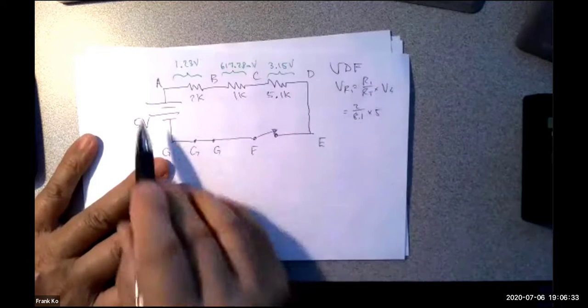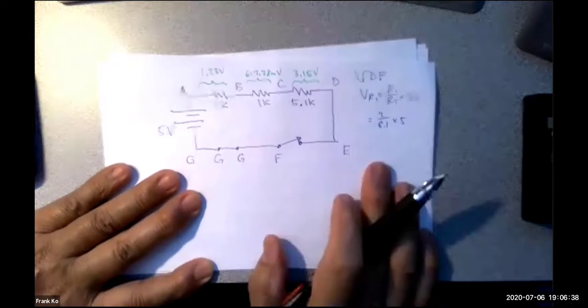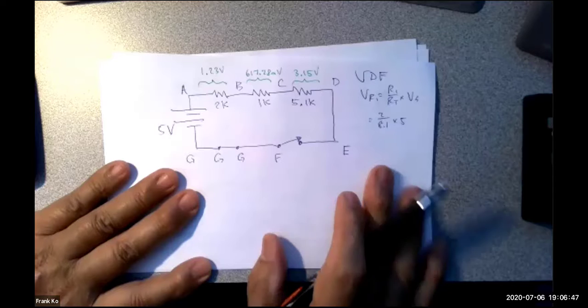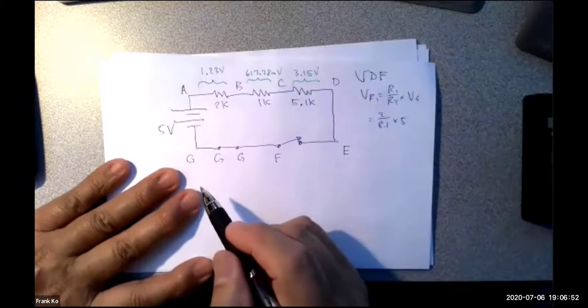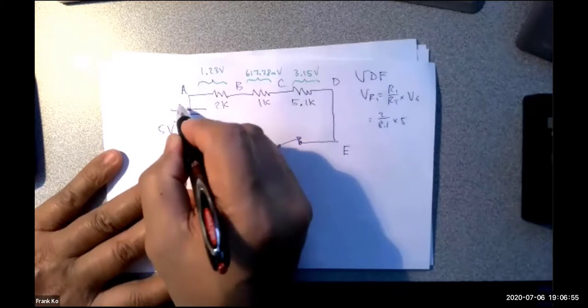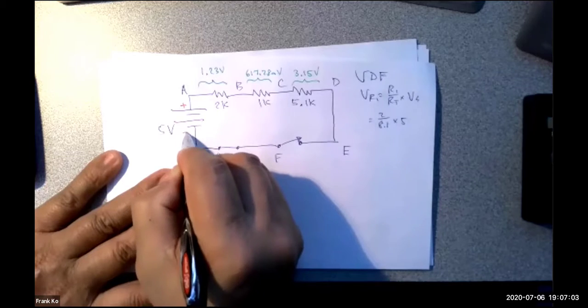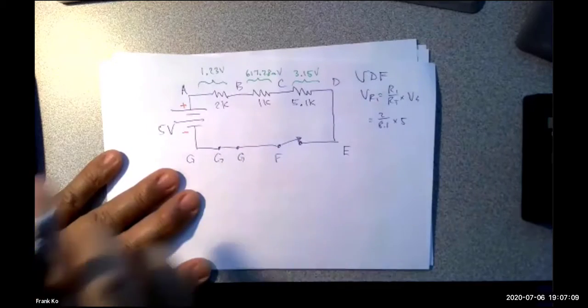Okay, then the next thing you have to remember: what determines polarity in any schematic that we work on? Who remembers what determines polarity for any schematic that we work on? Carlos, do you remember? Kirsten, do you remember? The direction of the battery? The orientation of the plates of the battery, correct, yes. And in which direction does the battery push current? So the long plate is always going to be what polarity? Positive. Okay, good. And the short plate will always be? Negative. Good. The plates will determine the polarity of the source.